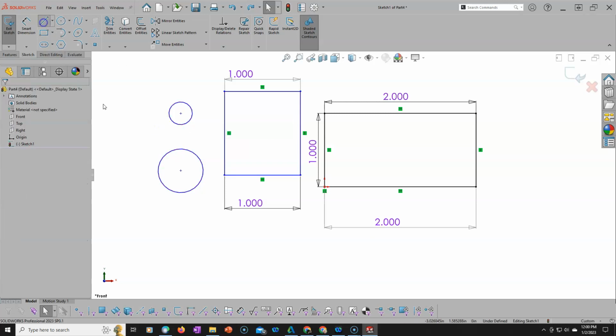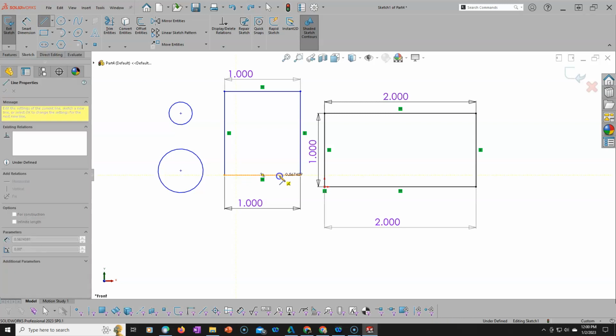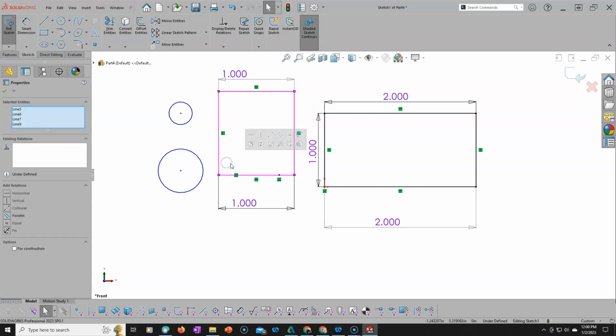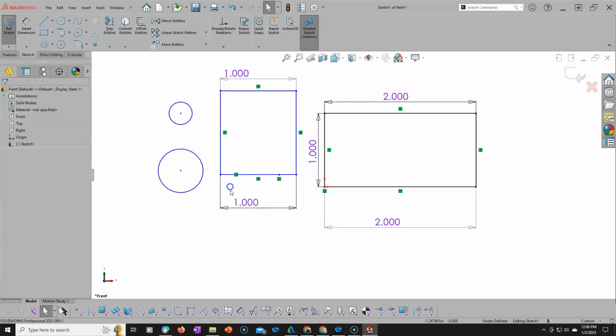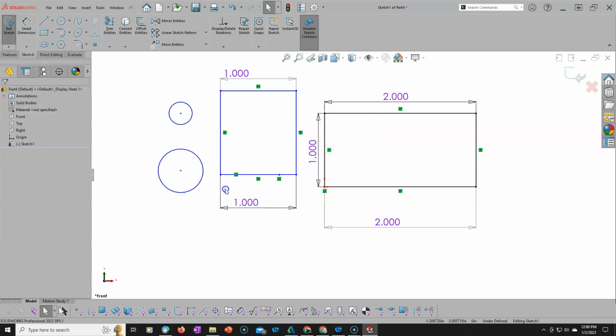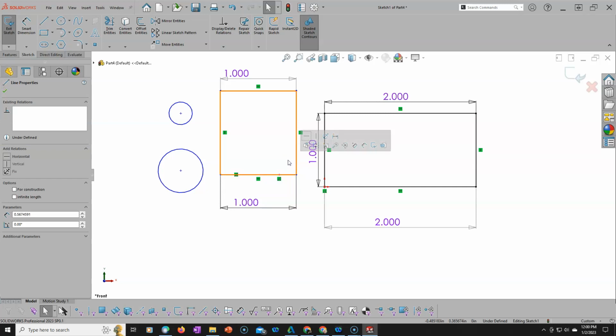So duplicates can be kind of problematic in that if I have a line on top of another line, I might be able to see those points. I don't really know where they're showing up, and unless I can move it or do something with it, then pretty much I can do the window pick. From left to right is everything inside of the window.